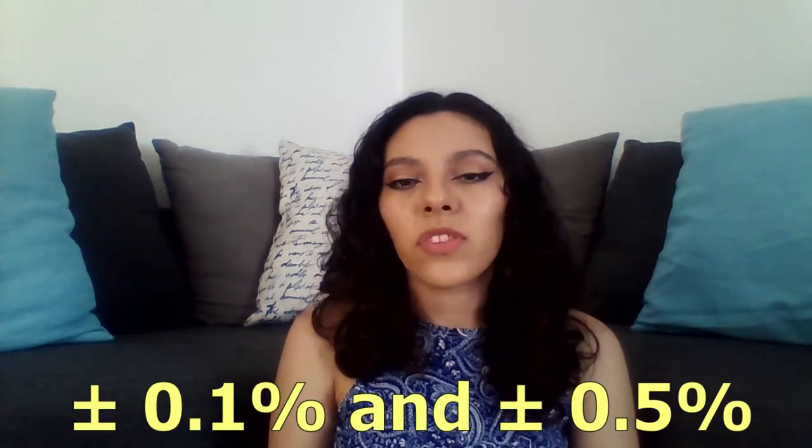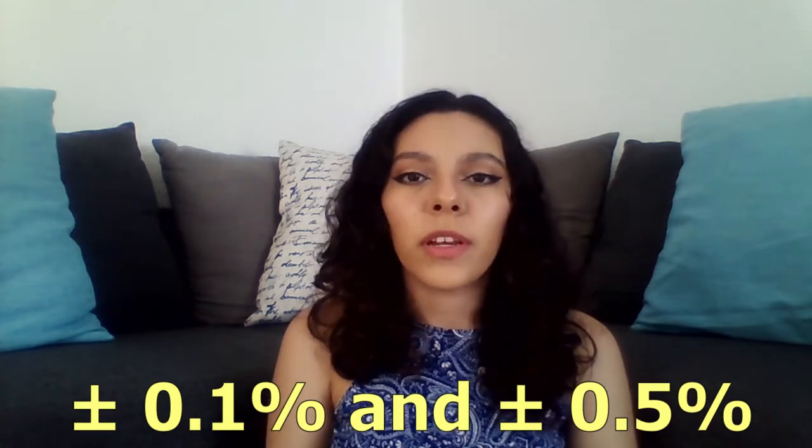The error in the diameters in the pipe and in the orifice is the root mean square value of the micrometric measurements made. The error in the differential pressure P1 minus P2 is given by the precision of the device, which is typically plus minus 0.1% and plus minus 0.5%. The error in the density measurement is given by the density instrument or the pressure and temperature compensation devices, in which case the root mean square of the corresponding errors is added.